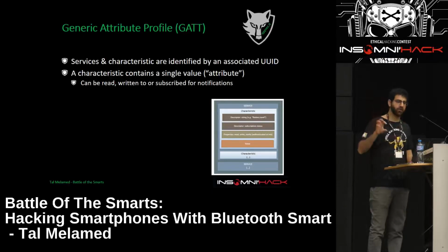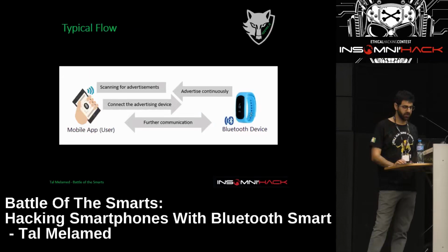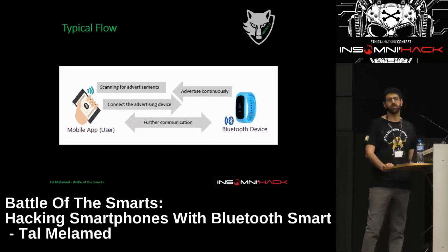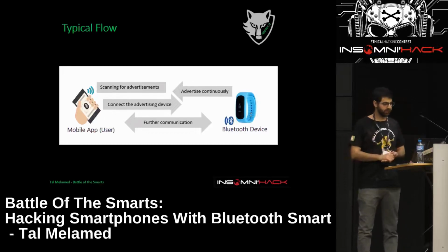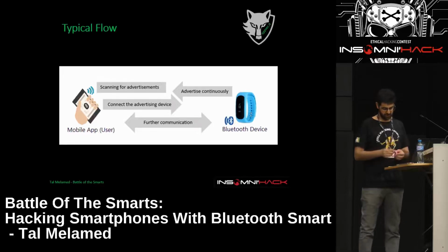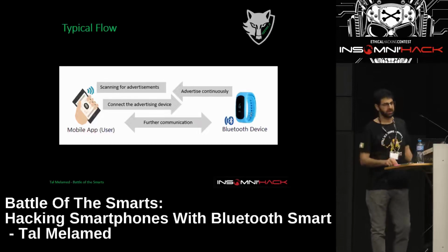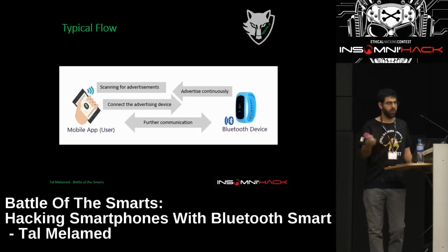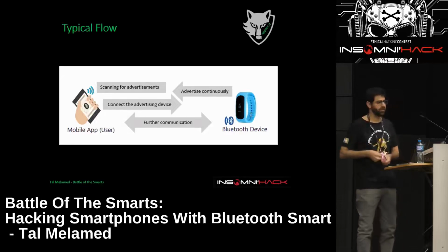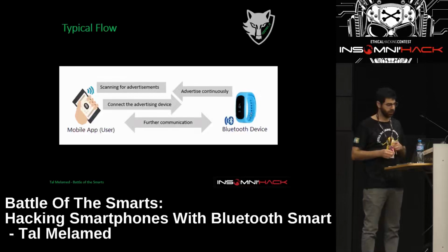Okay, and then for each service, this is how the application knows how to communicate with the device. Typical flow of the Bluetooth communication. So BLE, because it's so power efficient and low cost and doesn't require much battery, is continuously advertising itself. So if I want to connect to a device, here I have a smart watch, we'll see later how we interact with it.